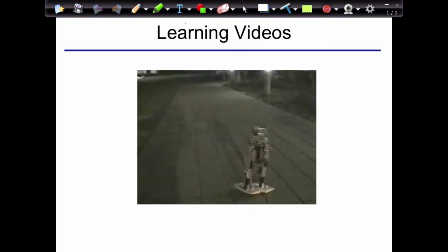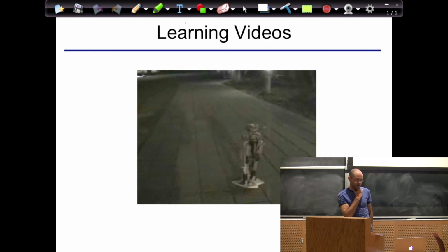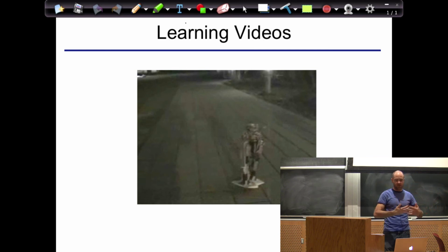Even with all the tools we have today and all the things we've done to talk about passive walking, I still think this was a pretty good solution for that robot. Modeling the dynamics of that rolling contact is pretty tough. To make it work right in practice, I had to add silicone to the feet, and it deformed in non-trivial ways, so modeling the contact dynamics is pretty tough. The actuators were crappy at best. I really think modeling that would have been pretty tough. And the magic, when these things work, is when you can find a few parameters that meaningfully parameterize the control space you're interested in.